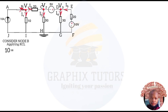Now if you look at which currents are leaving node B, you look closely, I1 is leaving and I2 is leaving. Look at the arrows. They are both moving away from node B. The law says the current entering equals the current leaving. So since I1 and I2 are leaving, they are partners in crime. Are you with me now? So we are going to say 10 equals I1 plus I2. I'll term that equation 1.